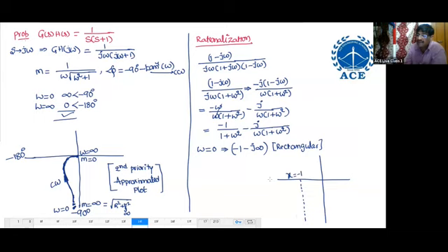Here at omega equal to 0, this is minus 90. So at omega 0, the polar plot should start with a straight line of x equal to minus 1. Then it should move towards minus 180, and end at minus 180 with a magnitude of 0.